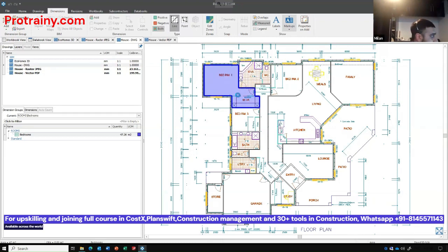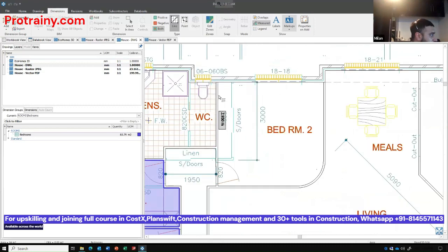So I use L, and this uses the polylines that have been used in the design software. And see, I can pick up these very quickly. So if the designer has used polylines, it helps us massively to pick up these areas. I won't measure them all, but you see how we work with curves.